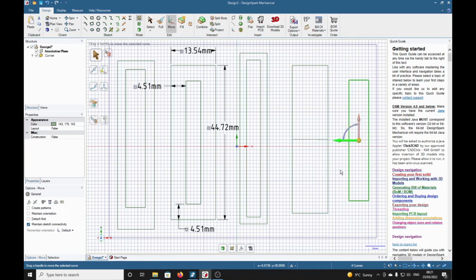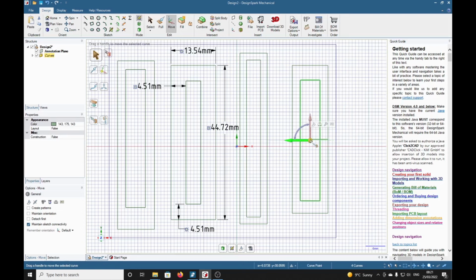Select the green arrow pointing to the left, and the up to tool, up to there, and then touch on the triangle. That jumps into the center laterally. Then go to the vertical one, select that, again up to and select the line, and it pops up the center vertically. And we can now just delete that.